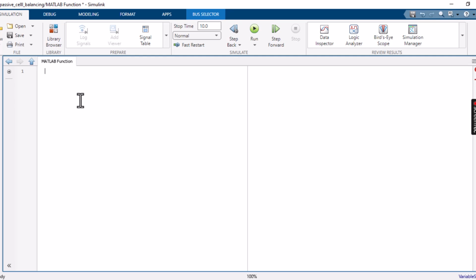So what I am typing, let's say function, in small letters. See what I wrote: s1, s2, s3 is equal to fcn, in small brackets, u1, u2, u3. Actually it should come inside, so press Ctrl X and go inside, Ctrl V.